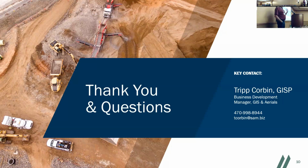What I've had to do with data like that, and this is no fun, is at least know what state it's in. So you open a map, you bring the drawing file in, it tells you there's no coordinate system, and you just have to start trying different coordinate systems until it pops in. Oh yeah, there it is. I've done that in Canada and elsewhere.